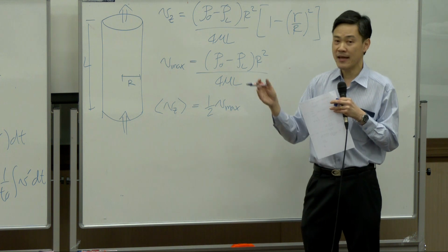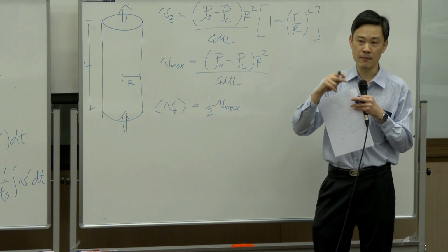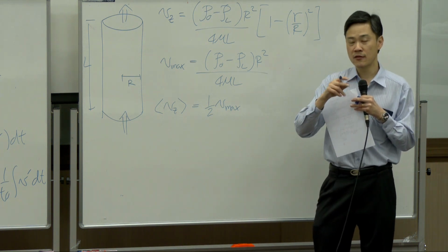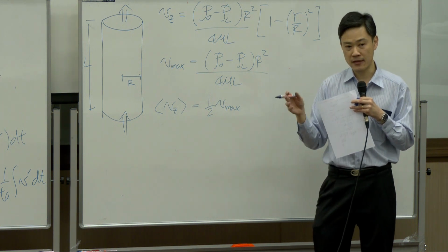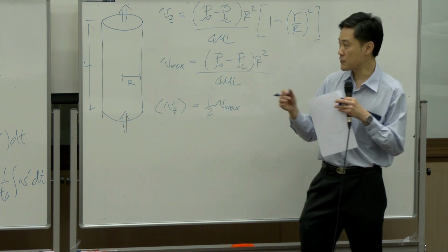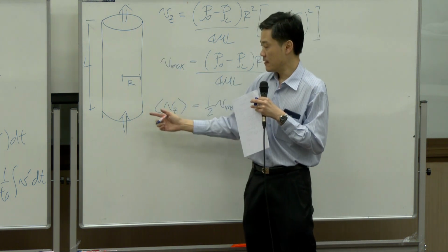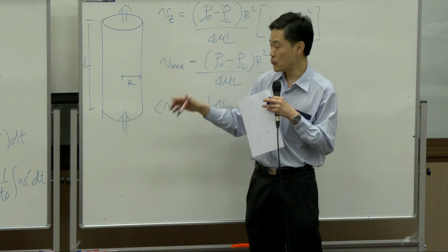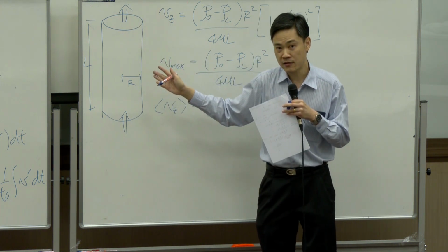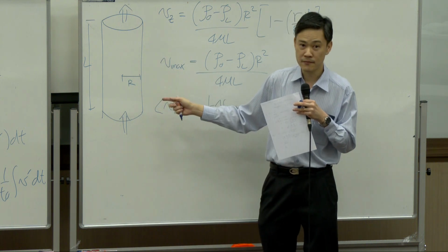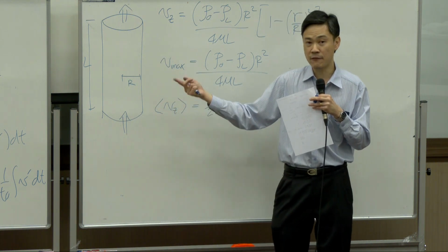In unit operation 1, or in fluid mechanics that you learned so far, you balance from in and out. That is called macroscopic balance. If you consider flow in the pipe, after you do the in and out balance, or if you use the Bernoulli equation, you can get the pressure drop. You can calculate the pressure drop in the flow in a pipe.